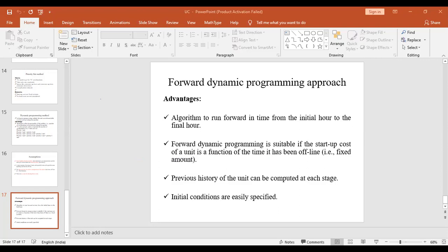The next set of constraints are the transmission line constraints and the network security constraints. The transmission line constraints are essential in calculating the transmission loss, and the network security constraints are essential in calculating system violations, which add to the complexity of the constraints. If the complexity of the constraints increases, the number of systems under study will also increase. So it is essential to account for network security constraints and transmission line constraints when solving the power flow analysis of a power system network.